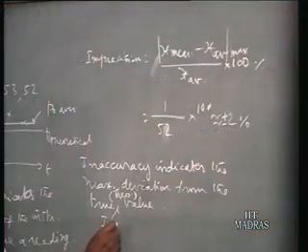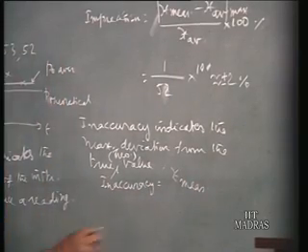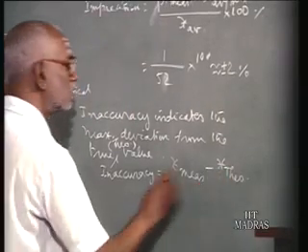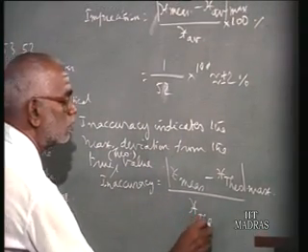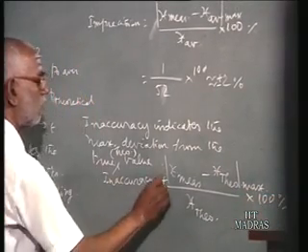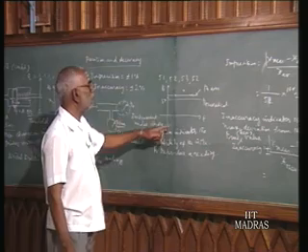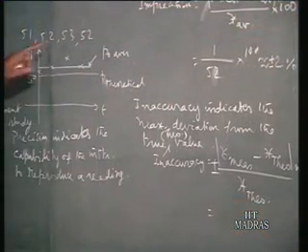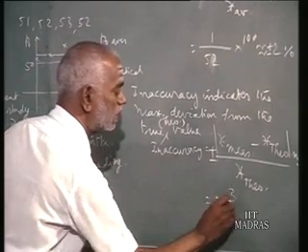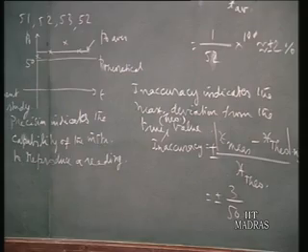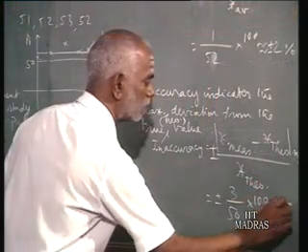Now here, in terms of equation, inaccuracy is equal to x measured minus x theoretical or true, whatever it is, the maximum deviation from theoretical in a set of readings, divided by x theoretical into 100. In terms of percent, we always put plus or minus, as we have done for imprecision. So for this instrument, the maximum deviation x measured minus x theoretical: 53 is the maximum reading, because 50 is the theoretical value. So the maximum difference is 3. So plus or minus 3 divided by x theoretical 50, because that reading is obtained from the standard instrument. 50 is always the theoretical value. It is maintained constant. Into 100, this is equal to plus or minus 6%.